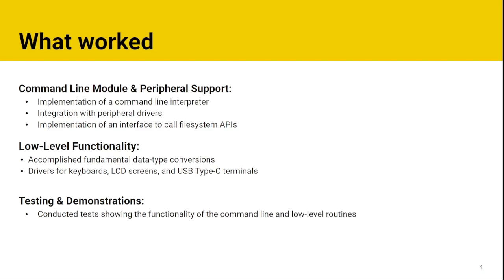For low-level functionality, our project successfully implemented drivers for USB Type-C connected terminals and USB keyboards. Both of these are translated to UART signals through hardware on the C3 board, and our UART driver is able to work with either of these inputs to receive characters from the user to be passed to the command handler.